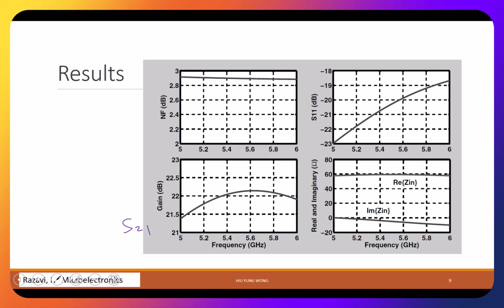You cannot have the same layout because your transistor width will be different. Yeah, but this is only 3 transistors, right? But in principle, you can do this. After you have the layout, you just change the size. It should update. Now, if you're serious, they should have different layouts because you change the size, so the routing will be different to minimize the parasitics, right? But again, I am not trying to force you to do this.